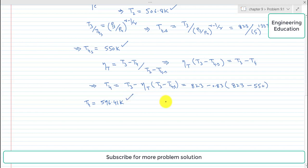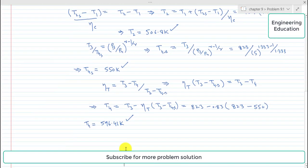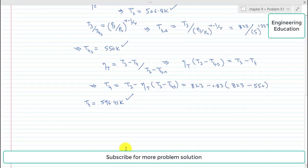Now it's very easy to find the work of compression and the work of expansion. Now using these temperatures we find the value of compressor work input and turbine work output using the expressions Cp into (T2 minus T1) and Cp into (T3 minus T4). I am directly putting the values in those expressions.